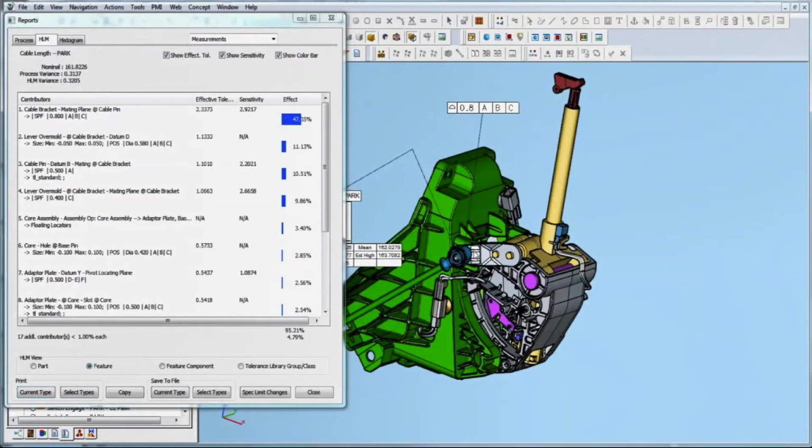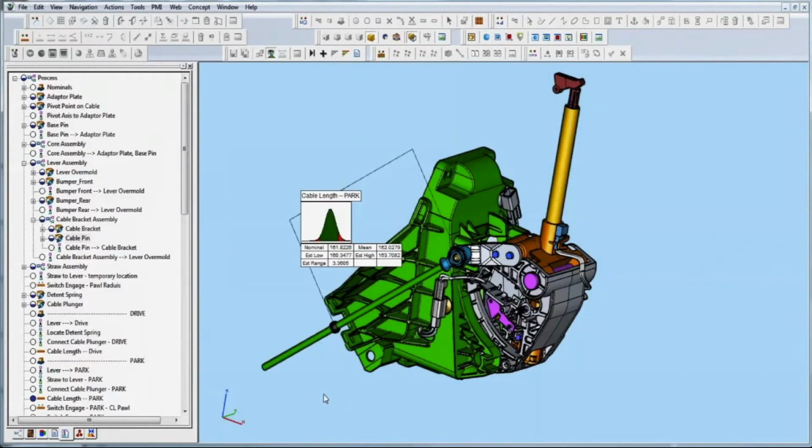If I stand on it, it actually shows it on screen, and it's the plane behind that pin. And if that plane tips, the pin tips with it, and it pulls that shaft in and out from one build to another. So, it's a great tool. It's 3D. I can report on this. And then these results can be documented inside Teamcenter against the requirements. And if there's a question on it, we can actually pull this model up to make sure what version of the math or what version of the tolerances we used to make sure everybody's in consensus that it was right.